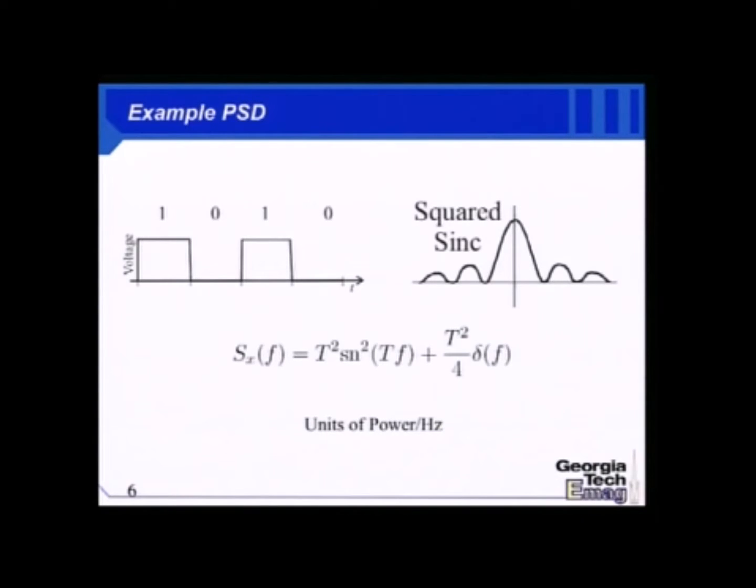It rings quite a bit. And so you will leak a lot of energy out of band if you use square pulses in radios. That's why almost nobody uses square pulses when you modulate data. But the principle is there. If I wanted to smooth things over, I could use triangles. Triangle of a certain amplitude and a negative triangle or a 0 triangle for my zeros, positive triangle for my ones. And of course, what's the Fourier transform of a triangle?